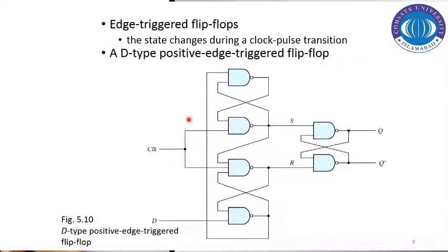Now let us see the example which we have to implement in today's lab session. Basically, in today's lab session we will be implementing the D flip-flop, that is positive edge triggered flip-flop. So the transition only happens with the positive edge of the clock, and this is the diagram showing the implementation of the D flip-flop. That is basically implementing with the help of SR latch, which we have implemented in a previous lab. So we can see that the setup of the latch here, and there is also a set of the latch here that is repeated, and same is the case here.